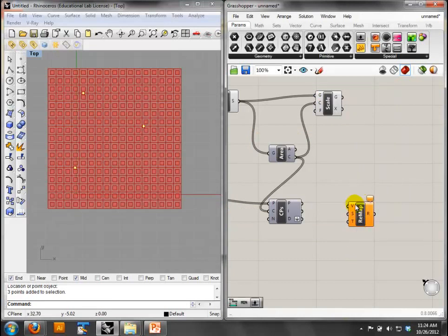This component, you feed it a list of values, like any range of numbers, and it returns those remapped to any range of values that you want. So I can plug in numbers from 0 to 1,000, and it can give me back those same numbers remapped to range from 0 to 1, which is really handy, right? Because then if I multiply anything by any other number, I can basically control that number, and I can make any kind of arbitrary number I want. Well, I'll show you what that means in a second here.